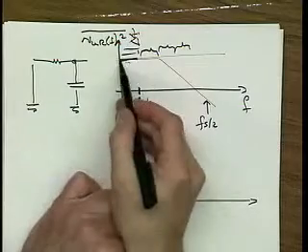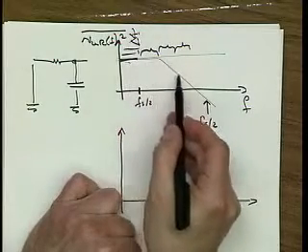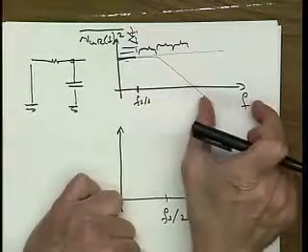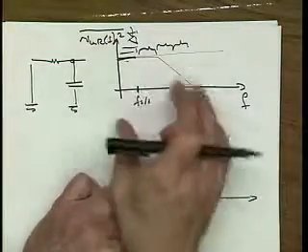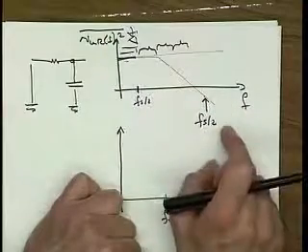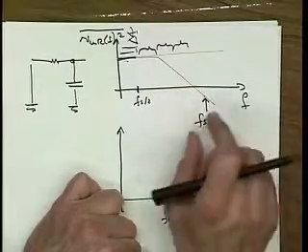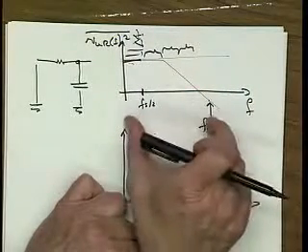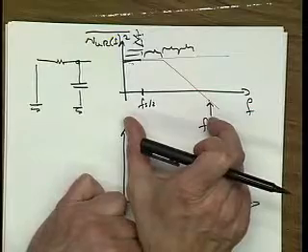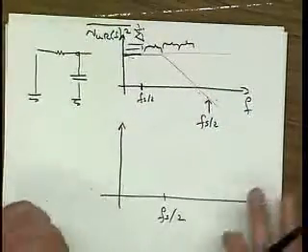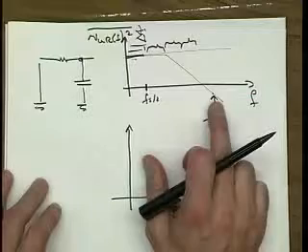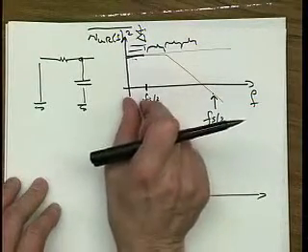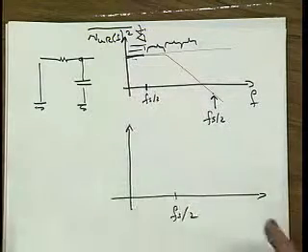Well, in the end, we are going to have a spectrum that pretty much looks just like our red shape here. Why? Because the power of this stuff down here, remember, this is really a log scale, otherwise this wouldn't look like this, is so low that it really doesn't change the shape here very much. So if we oversample this noise, we're going to see some kind of a low-pass characteristic in the sampled noise also. If on the other hand we undersample the noise, this case here, then we're going to see white noise.